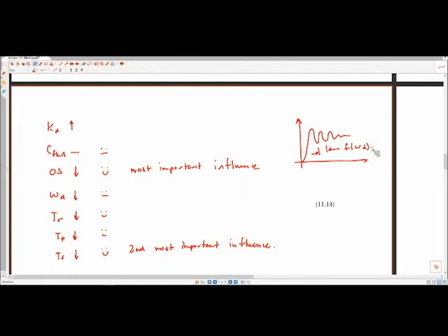So just another doodle, I guess, to follow on that. All right, so say for instance, I have some sort of signal and it's noisy. So that means it's like something like that, right? Everyone here from their measurements class or from other freshman engineering has seen noisy signals before, right? So the derivative, what it's doing is it's looking at essentially what is the slope of this line at every time step, right? And the noise, if you look at the slope, if I were to draw a line saying what's the slope of this section here, it's like that, right? It's pretty steep. And so if I put a large gain on that, that could have some really negative effects in terms of propagating noise into my input signal.